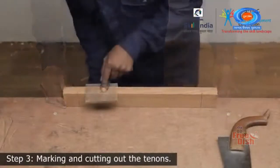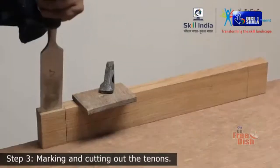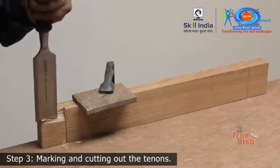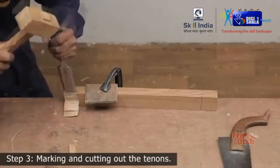Reset the piece on the clamp and cut from the other edge on both the sides. With a chisel, clean out the remaining waste wood from the edges. Remember to keep the tenon edges clean and sharp, as it will not fit perfectly into the mortise if the edges are rough.